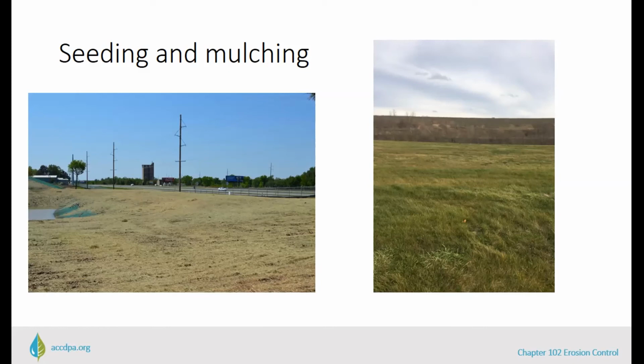Seed mixes vary depending on soils and activity. Native mixes and perennial species are best. For straw mulching, at least 3 tons per acre is the application rate. At this rate, bare ground is just invisible. The straw isn't matted or clumped, but provides a thin, uniform covering.